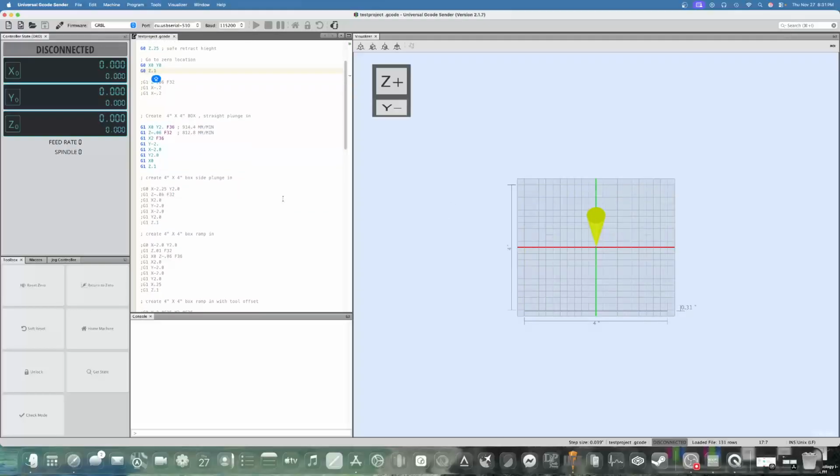Now the biggest problem you're going to have here in the finished part would be where it comes right here and feeds in. We got back over here, it's traveling over, gets up there and it feeds down. And if you ever machine one of these parts, you notice there's a radius left over from your end mill because it's feeding in on the side. It vibrates a little bit and it undercuts it.